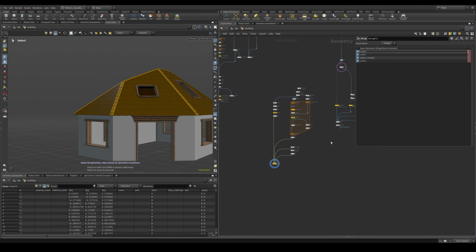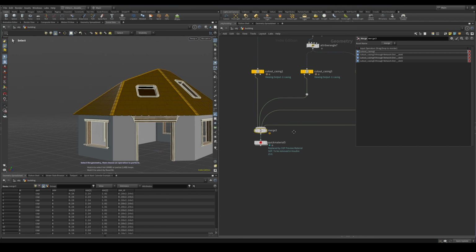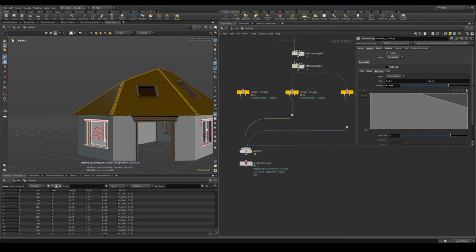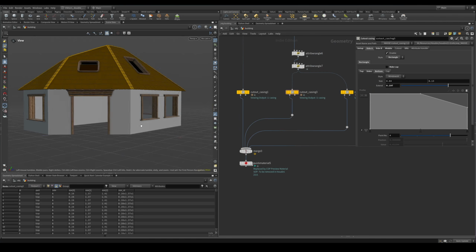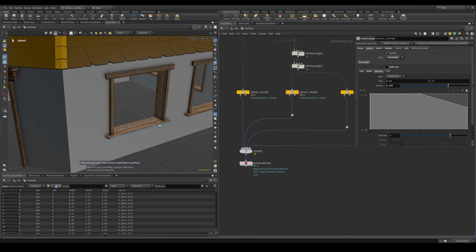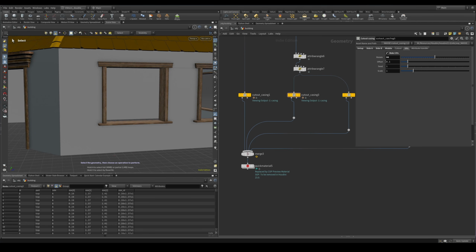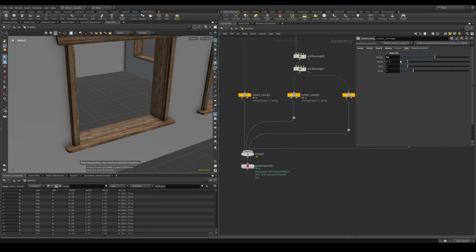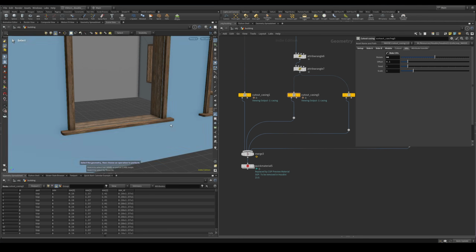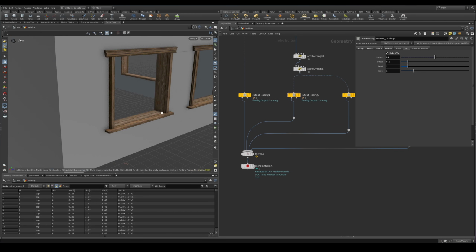Talk about the UVs very simply. So I have tried to make this HDA node as fast as possible. I am using a compile block. That means it's going to be pretty fast even with multiple geometry pieces. And if you want to make it a little bit faster, when you are actually creating your trims, your casings, you can actually disable the UVs. Since UVs do take a little bit of processing time, you can disable them and work on how your trims look and then enable UVs.